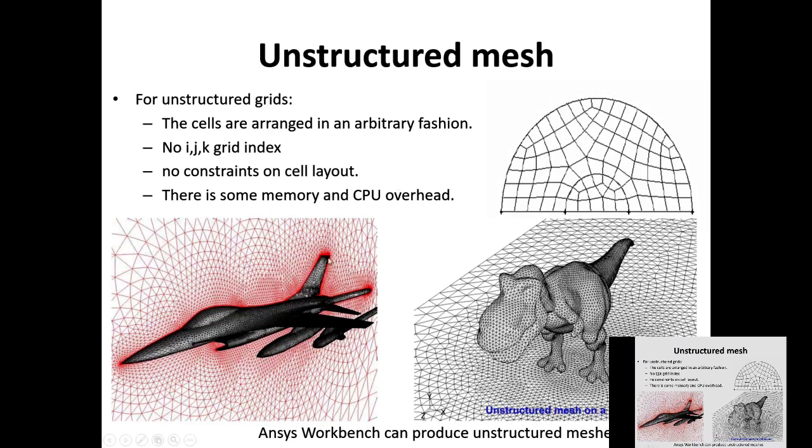For this one you have really fine grid elements here. For what? Yeah, good, to resolve the boundary layer. You need to have a good grid resolution here. Resolution means the number of grids that you have at a place.